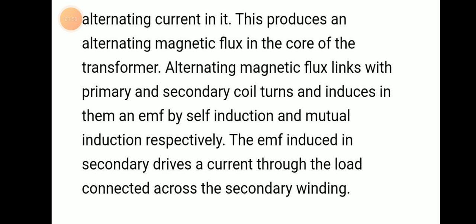This alternating magnetic flux links with the primary and secondary coil turns and induces in them an EMF by the principle of self-induction and mutual induction respectively. The EMF induced in the secondary drives a current through the load connected across the secondary winding.